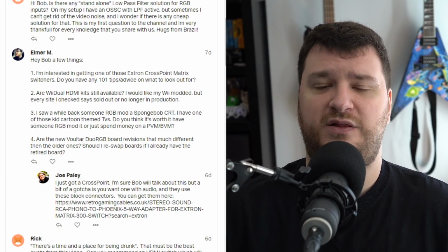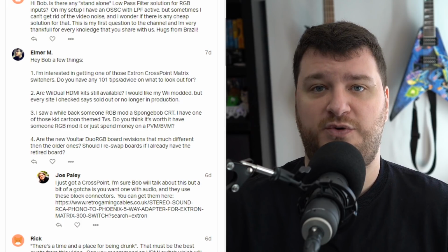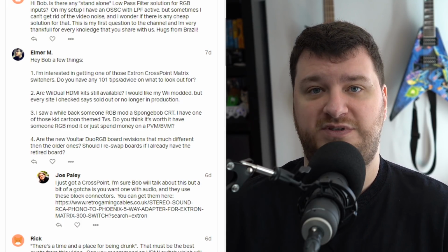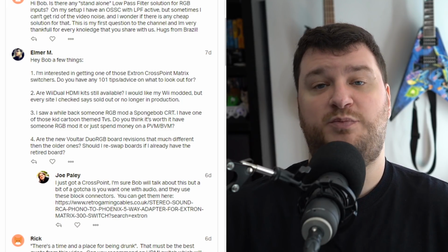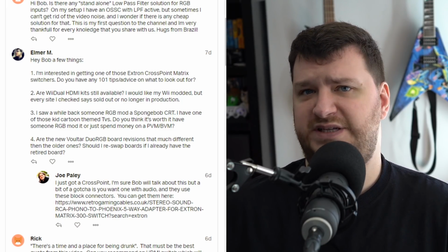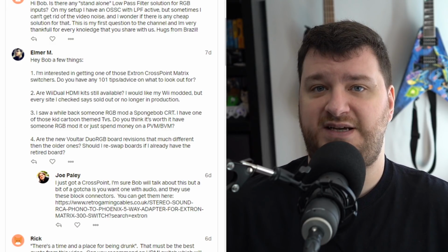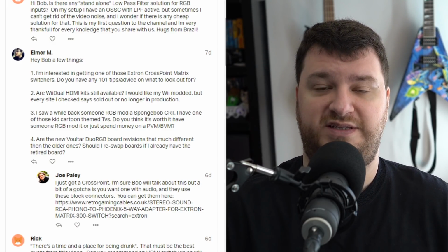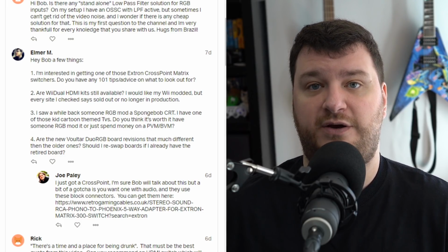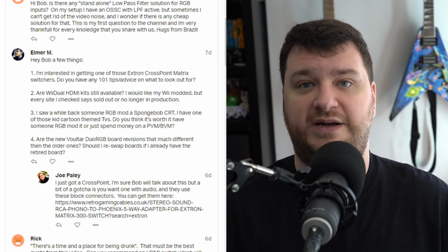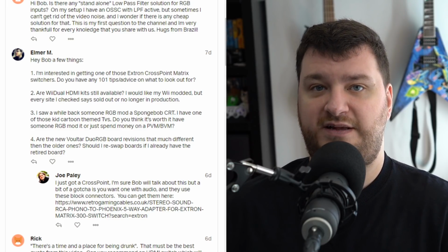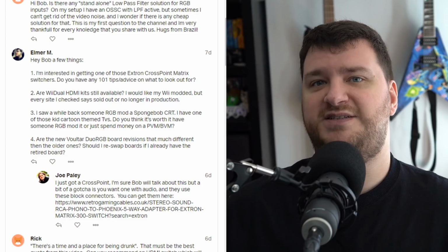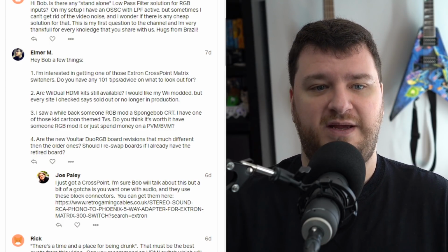Make sure that the consoles that you own that don't output C-Sync have some kind of sync stripper in the cable or some kind of solution. So for example, PlayStation 1 and PlayStation 2 as well don't output C-Sync natively. And you could do mods on both of them that will turn Luma into C-Sync, and then you just lose S-Video, which in my opinion is totally fine because you still have composite, which is arguably the easiest to use in some situations. And then of course you still have RGB.